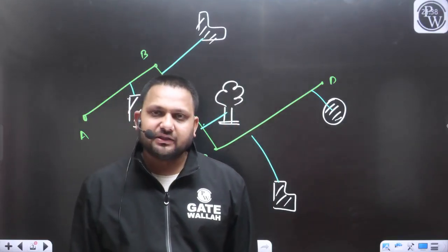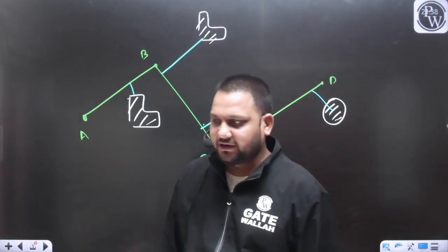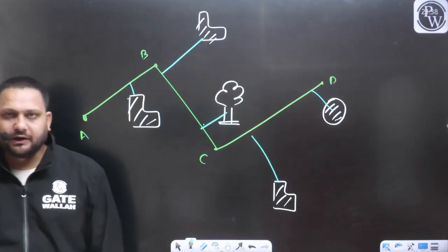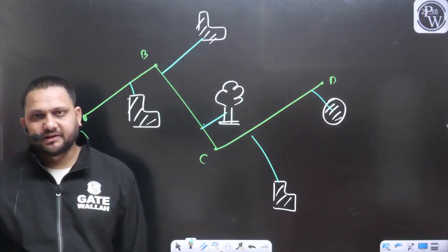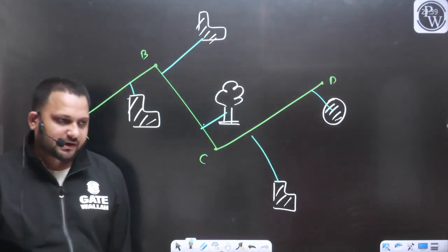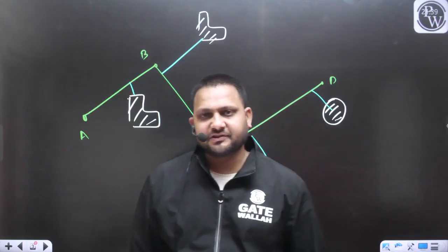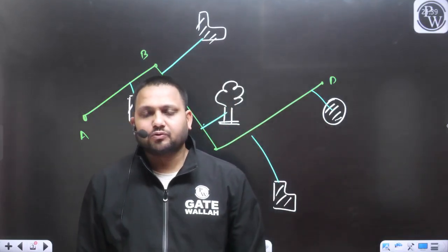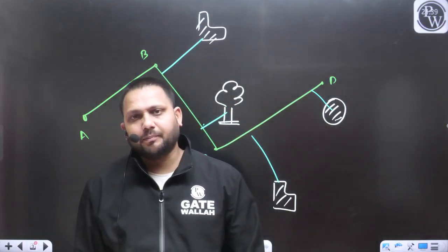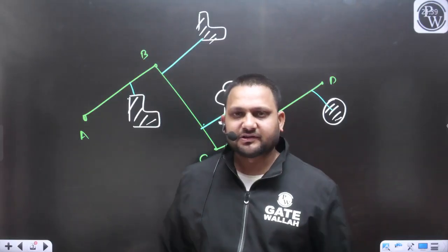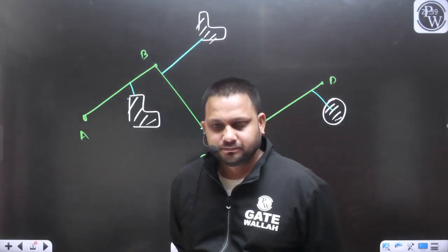So you can locate the position of the plane table, you can find the plane table station, with the help of two well-defined points. Well-defined points means that 2 points should be available on the ground, as well as on the existing map. If we are locating the position of the plane table with the help of two known points, that problem is considered the 2-point problem.